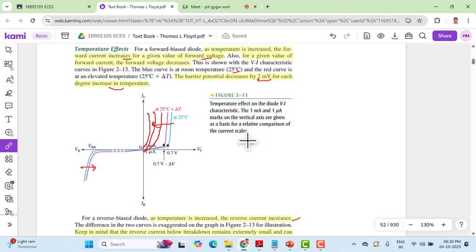We don't use diodes in those high-end applications. We generally use what is called CMOS, which consists of NMOS and PMOS. These are the basic elements in today's laptop or mobile phone, functioning within that as a switch. As I said, the diode keeps varying with temperature, but CMOS devices are relatively insensitive to temperature.